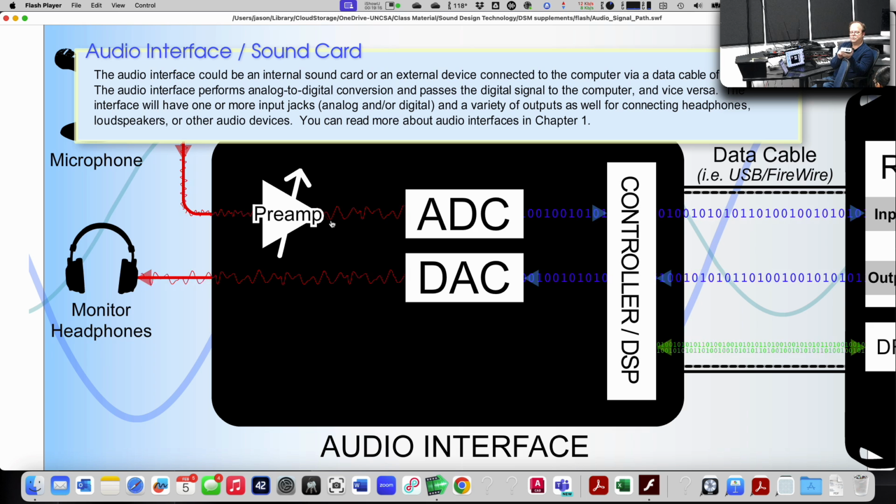This thing is also able to sample, I believe, up to 192 kilohertz, 24-bit, which is pretty good. That high of a sampling rate implies that there's a frequency response capture for this that is much higher than 20 kilohertz. So it's going to be able to encode audio frequencies much higher than 20 kilohertz.